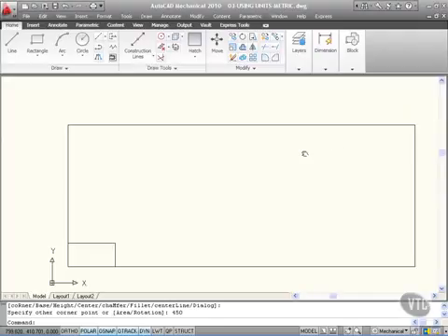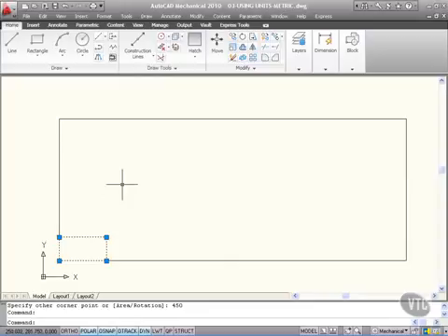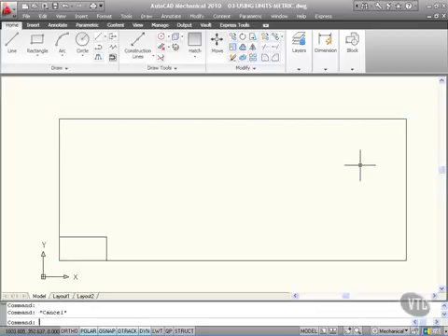If I just move along a little bit now, if I select this rectangle here, and hover on that grip there, it's 150 by 75. I'll hit escape to deselect. If I select that rectangle there and hover on that grip there, it's 1100 by 450. So as you can see, there's no distinction between meters and millimeters when you're working using your metric units. Similar process, slightly different display though to imperial units.